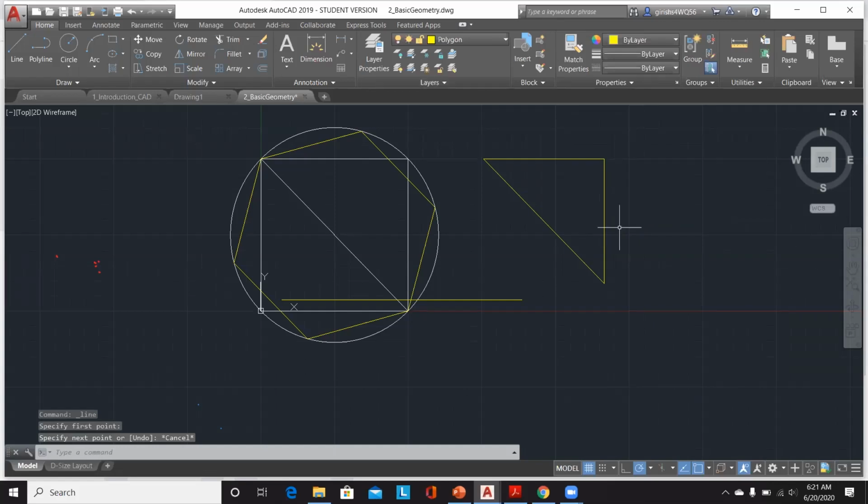The next toolbar that we have to pay attention to is specified angles, which is the polar tracking. Like when we are drawing our line segments, we wish to draw these line segments in multiples of angles that are required.